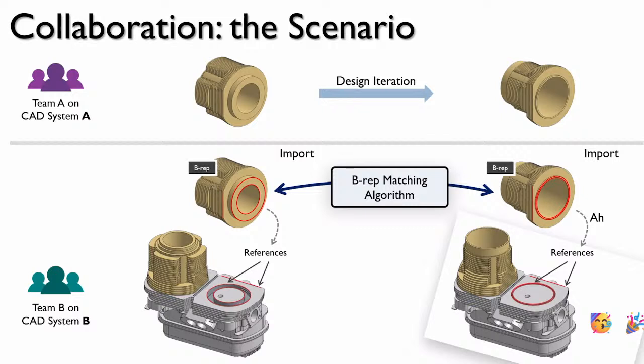And if CAD vendors wanted to be less copy-cat of each other, they would totally export that, but they don't. So the problem here is that the common interchange format is just geometry, B-reps. And all this extra metadata is unique to that program. For example, this naming scheme in some programs might be history based, in some it might be geometry based. Some people might be exposing this correspondence, some it's an on-the-fly computed thing, because these correspondences aren't entirely robust all the time either. Right, I'm aware of that issue, yeah. So it seems like basically the lowest common denominator is just to assume all you have is a B-rep. You just have to go from that.